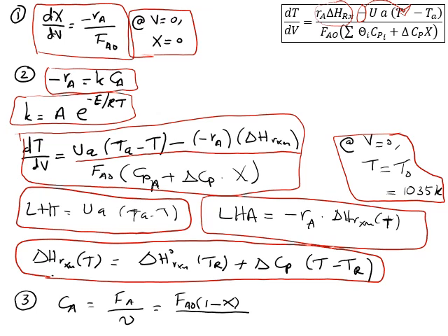It's a gas phase reaction. Therefore, probably epsilon is variable. And so I write epsilon equals epsilon naught times the 3 correction factors. First one related to number of moles. Second one related to temperature, T over T naught. The third one is related to pressure, which is P naught over P. Okay?